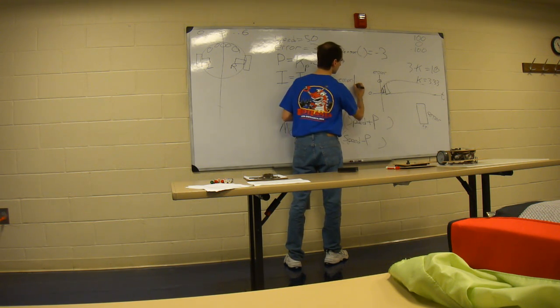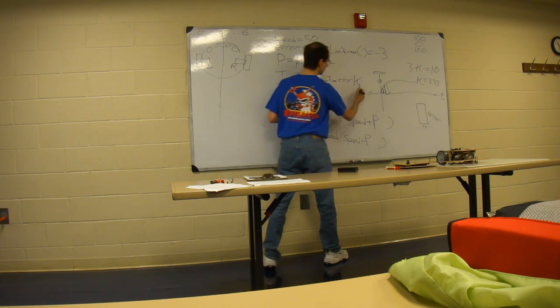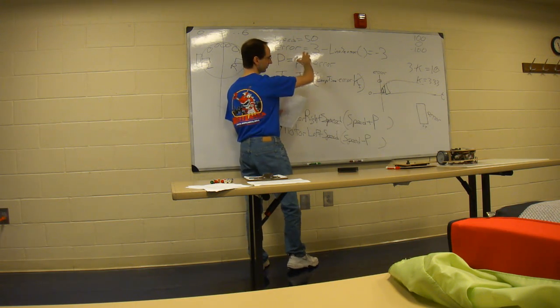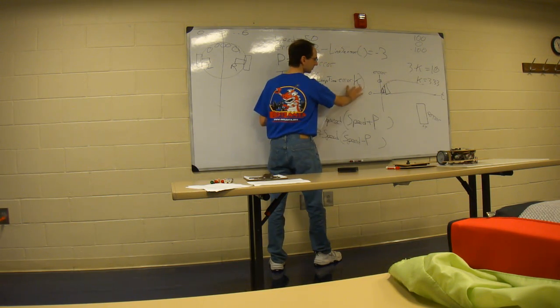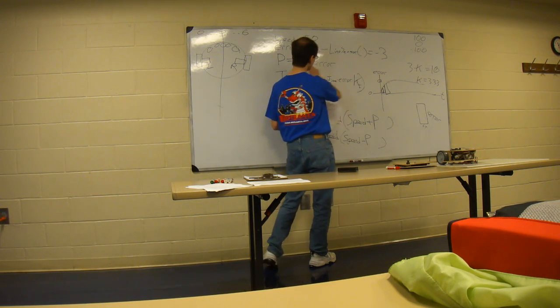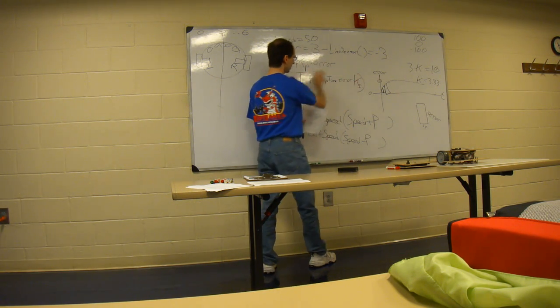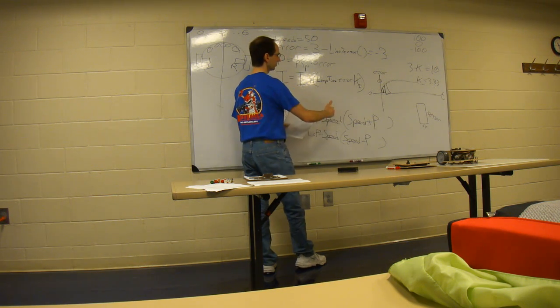And we still want a constant. This is going to be a different constant. This is going to be Ki. We want that to be separate from the other one, that way we have an adjuster for this term, and now we have an adjuster for this term. And that's all Ki is. Just like with the proportional term, here again we want to be able to adjust how much I is influencing our feedback loop.